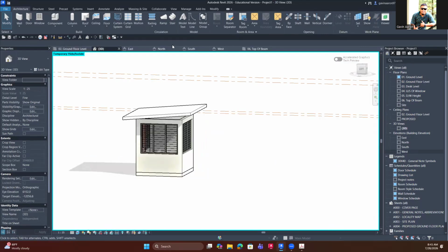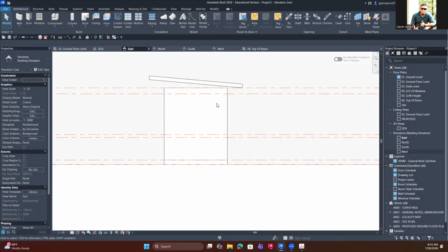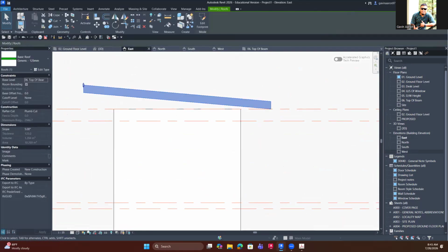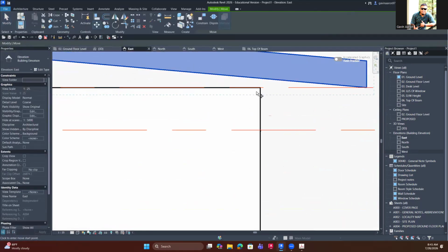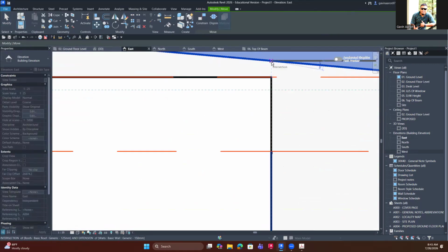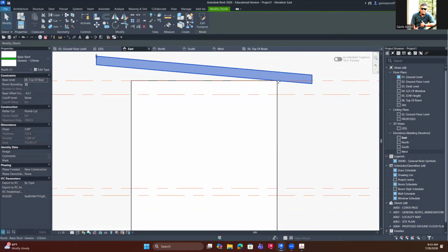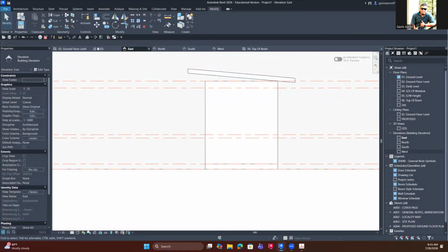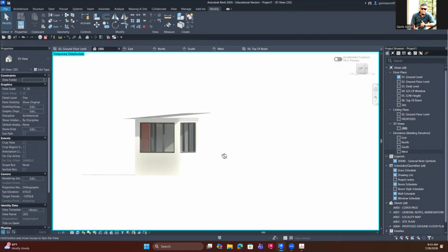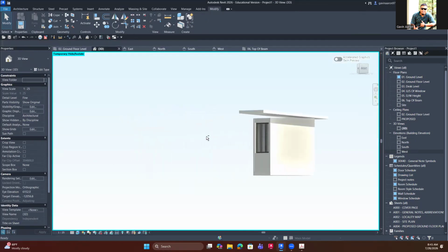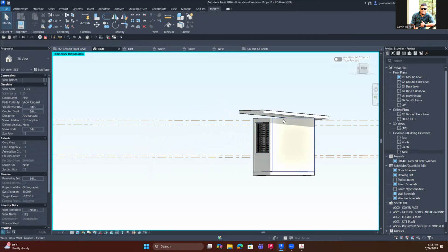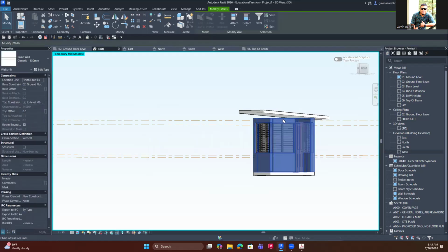Okay. Go back to your east elevation, and you'll make sure that your roof is sitting on top of beam. Okay. And then what you need to do now, how can you close off that space? This space here. So what you need to do, you put your cursor on top on one wall, you press tab to select the whole chain of walls, click, attach, then you attach top to the roof.